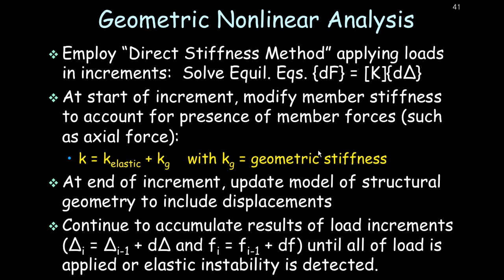All right. Well, any time you go to a nonlinear analysis program, my best advice to you is you actually need to do what's called an H convergence. And that is you run it for 10 steps, you get your answer, and then you say something to the effect, all right, what would happen if I cut the increment in half and use 20 steps? And so then you run it for 20 steps, and you'll find that the change was nothing. There was a small change, 1% or something like that, and you conclude that you've made the step size small enough so that you're good to go. All right. So that's one way to get there.